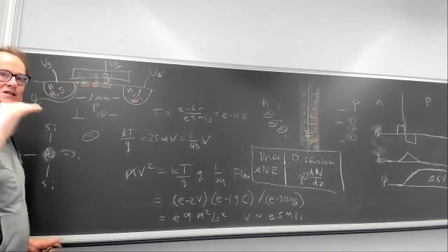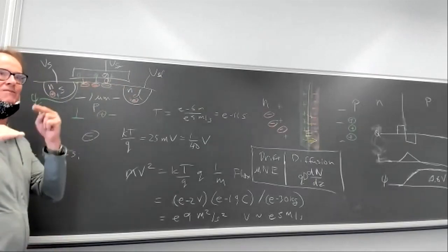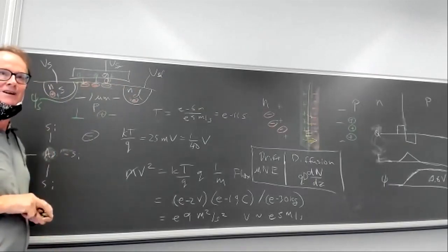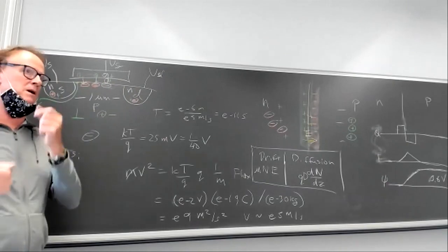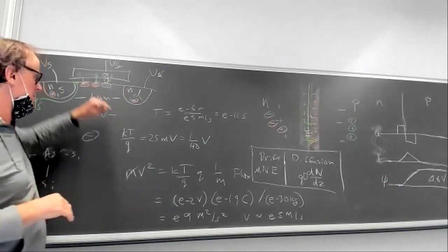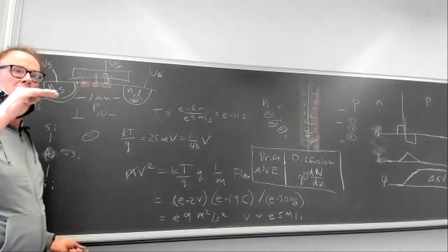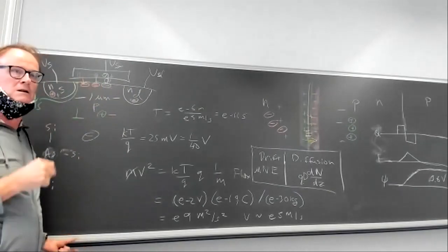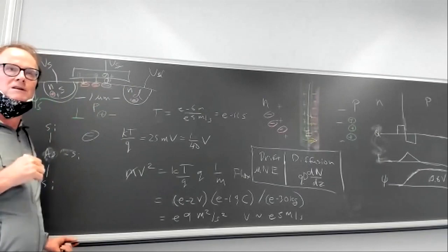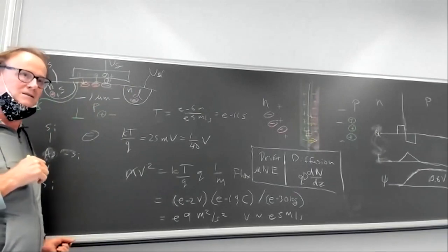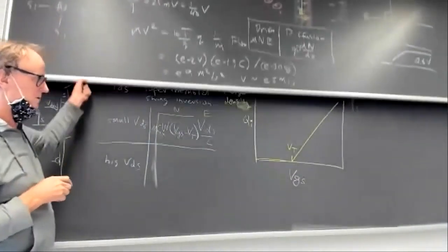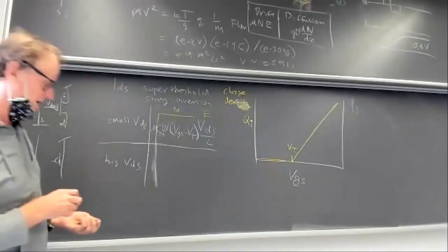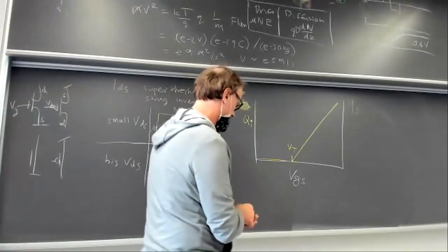And that's designed to adjust the threshold voltage so that the N and P FET thresholds are roughly equal. For logic circuits, you want the N and P FET thresholds to be about the same. So they always do this little implant of a certain amount of donor and acceptor just to adjust the threshold to the good level for logic circuits. Is it clear? Okay, so that's what the charge density looks like as a function of the gate source voltage. Now, what does the potential look like?